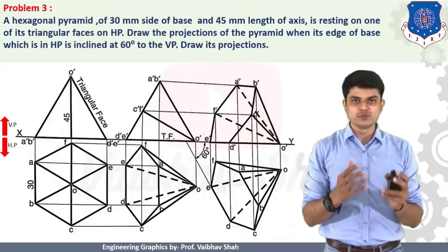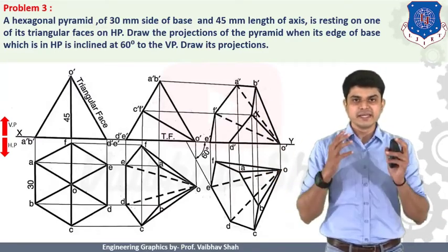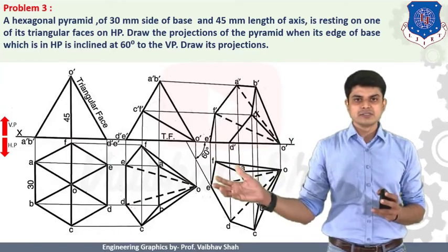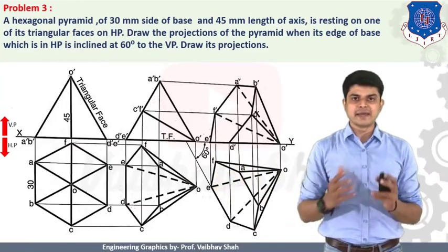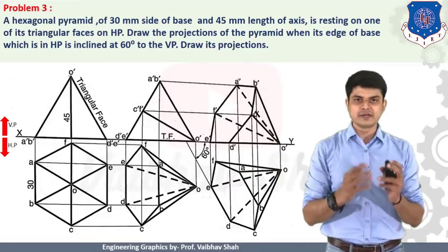Thereafter it is very easy. You should draw the vertical lines from each and every point and the horizontal line from each and every point in order to get this hexagonal pyramid in your HP. Now, let us find out the dotted line of the middle portion.